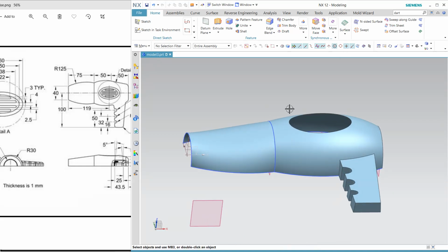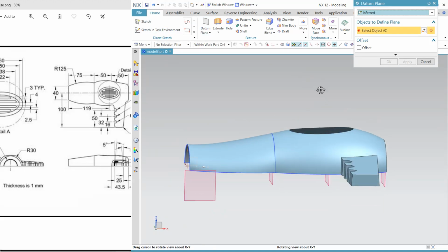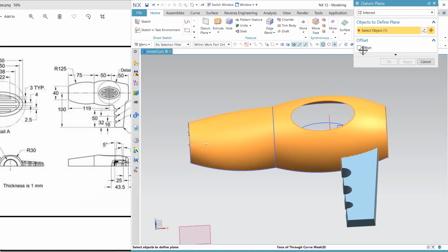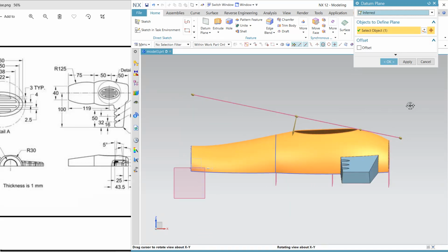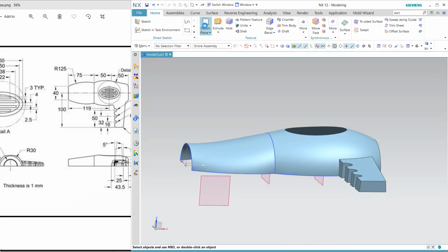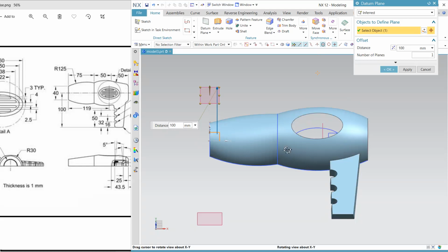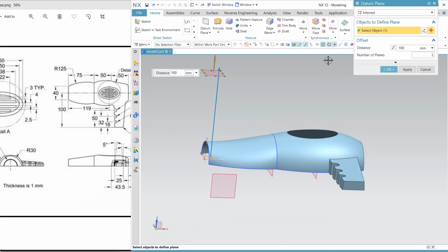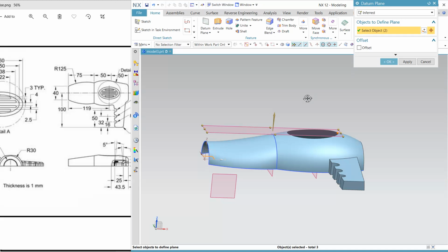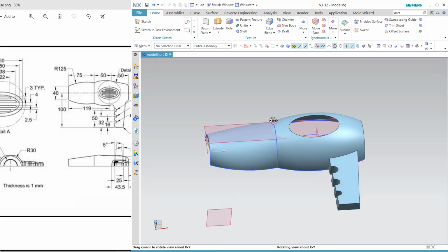And from the top I'm going to create a plane. So my plane is, click here, it is tangent, not it is not properly, basically it is not the proper. So click here, from this to quadrant of this, and offset 6 in reverse direction. Okay, so this plane is my working plane.